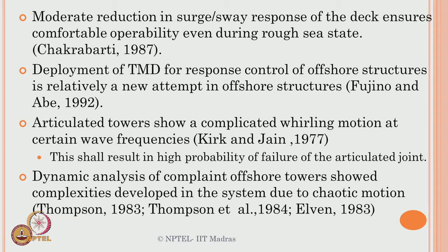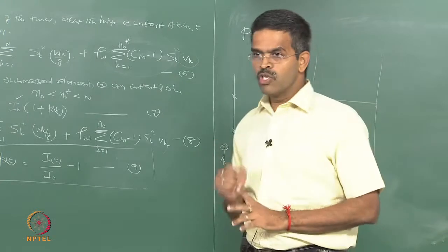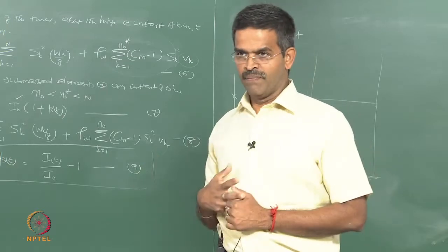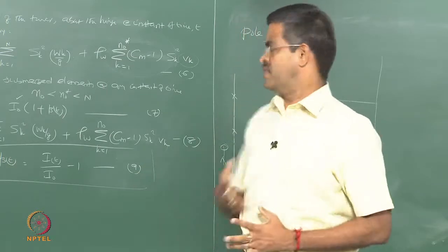Now once we agree that yes, response control becomes an important factor to control the responses, then Chakravarti 1987 pointed out that the deck ensures comfortable operability when you control the response even in rough sea state, and then people have used this tuned mass damper concept in the buildings, not in offshore structures, but of course Fujino and Abe attempted this, a new concept in offshore structure, and proposed this that can be used. So I should have a mass tuned for a specific frequency which should be attached as a secondary mass system to the primary system to tune the response of the primary system.